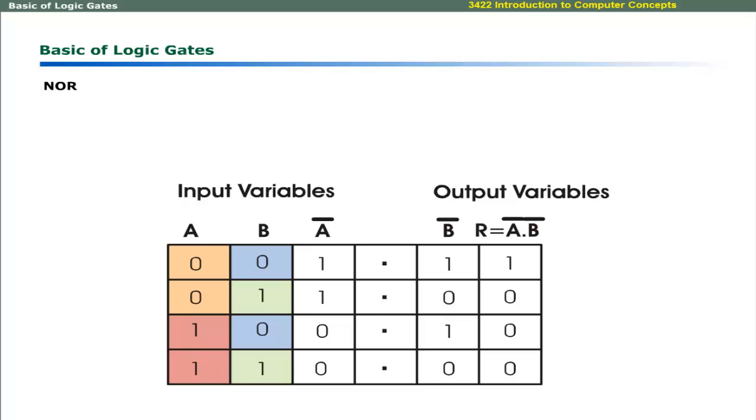The truth table for complemented OR gate is represented for 2 variables like this. The input variables are complemented and logical multiplication is performed to get the result. The result of complemented OR gate is 1 or true only when both input variables have binary values 0 or false.